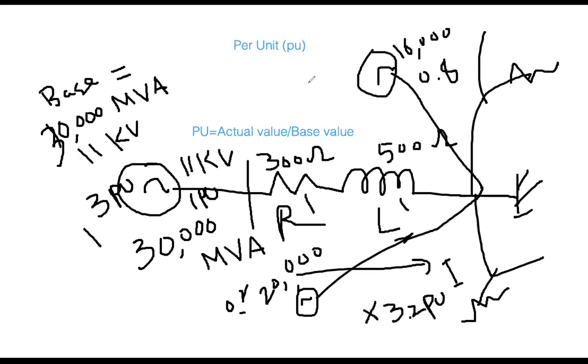You have a real power network, and now you need to analyze the voltage and current for a hugely interconnected system. At that time, at first you convert into per unit quantity. Then once you get your desired value, whatever you are finding out, at last you convert back into the actual quantity. So the meaning is the same. You will get the same result.